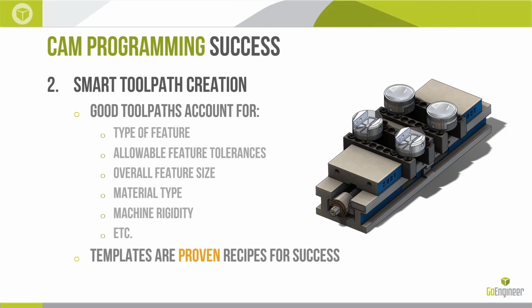All of these are going to help you attack how to create good toolpaths. And as I mentioned before, templates are a proven way of handling this scenario a little bit more elegantly. A template typically would allow you to program a part, save it as a template, and then later, as a programmer, access it.